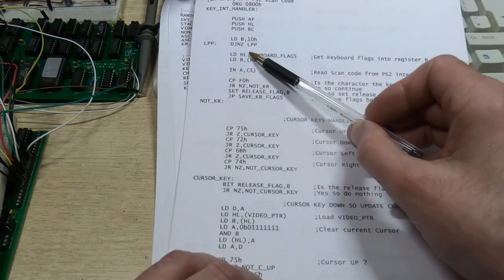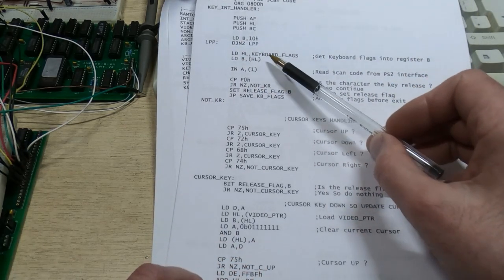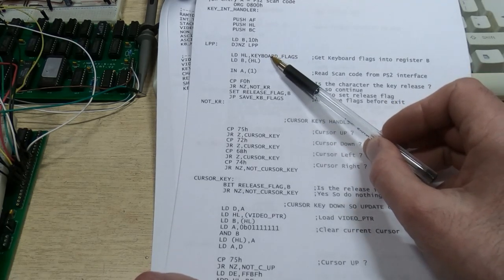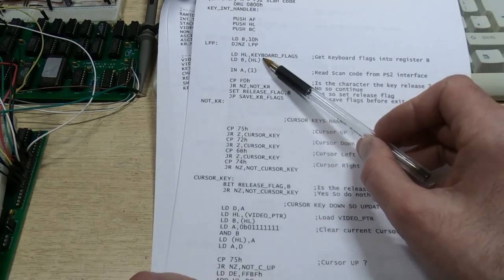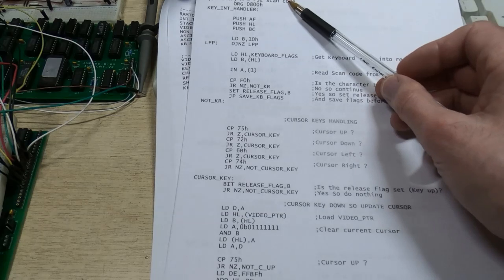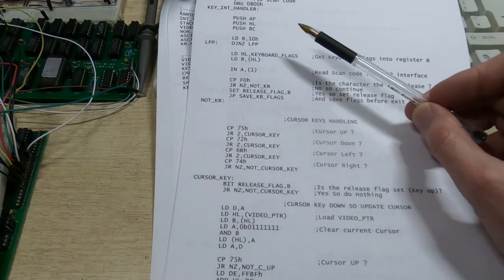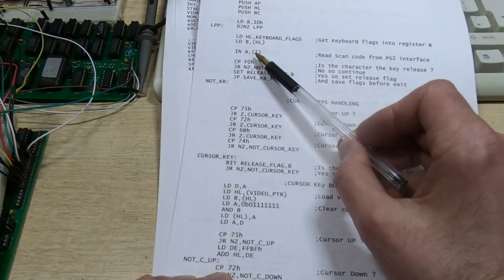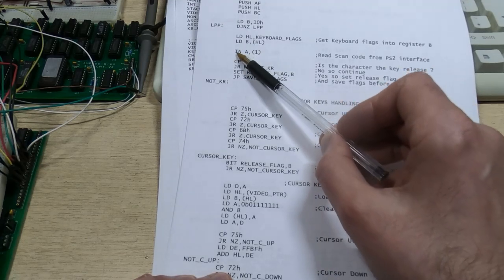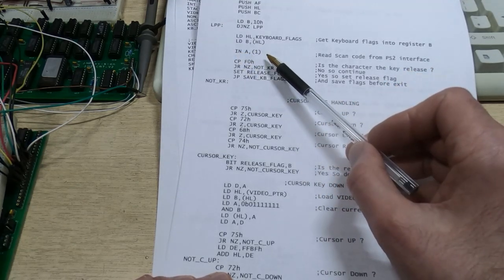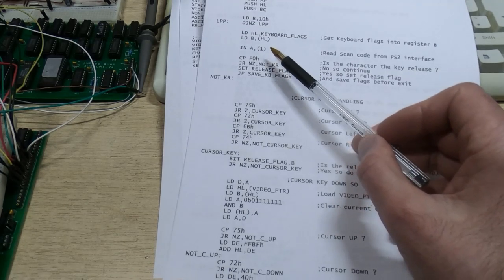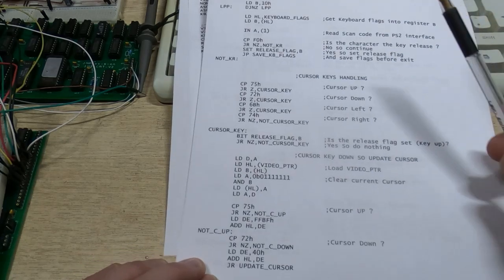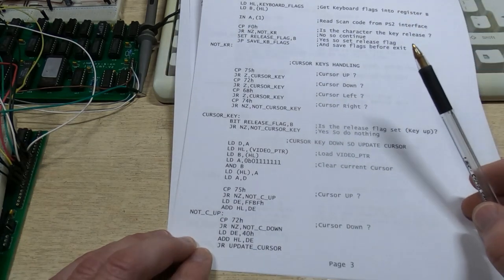We've then got a load of the keyboard flags, so we want to load the flags that have been saved. These are saved into a location of the DRAM, of course, our main system RAM, but it's in the common RAM area, so we'll be able to run this interrupt handler irrespective of which bank is selected within the system. We then read the byte from the PS2 interface, and you recall this also resets the interface, so it will then be available to accept the next character, and it can be doing that while we are continuing to process the data. It's a very efficient way of handling the key presses.